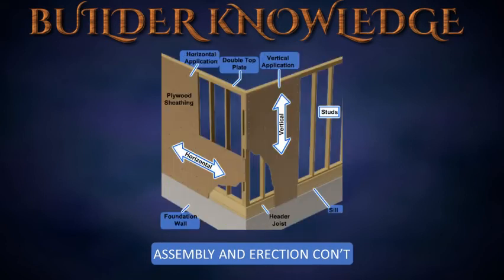Once completed, we are now ready for plywood sheathing. Ensure the first panel is plumb along the vertical edge and level along the horizontal edge. Secure the panel with nails, screws, or staples at the corners. Snap vertical chalk lines to mark the location of intermediate studs before installing nails or screws.